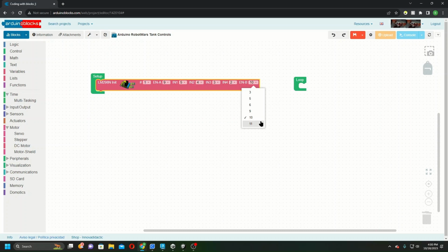Because we're using digital pins to control it instead of a direct increase and decrease of the power, with these pulse width modulation pins, the motor controller that we connect to, the L298N, is going to take a look at how frequently the signal comes in, and then use that frequency to determine just how strong of a power output it should put out to the motor.